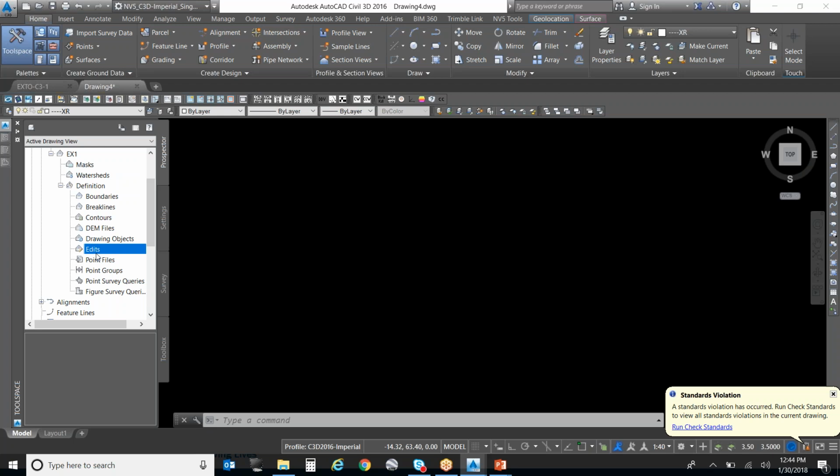Or the monument is in a monument well and 3 to 4 inches below your surface, up or down and frequently not flush with the surface. Correct. Any dips, right? We send our surveyors out to get a lot of dip information for existing sewer, storm drain manholes. Any dip information we obviously do not want to include. So we need to exclude that as part of the surface point group.